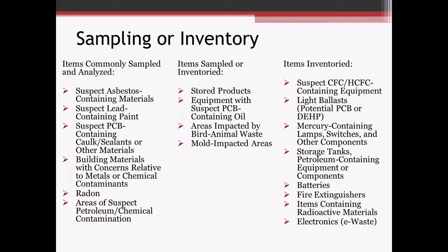Equipment with suspect PCB-containing oil. A lot of times you evaluate that on the age of the equipment, whether it makes sense. If it's really old, it might not make sense to sample. Just assume it's got PCB, especially if it's energized and active, and rather than shutting it down and taking it offline, you might just assume it. But if you have some old equipment that's de-energized, and nobody knows what or when it was installed, it might be a good idea to go ahead and sample that for PCB, and then you know if you have to treat it differently.